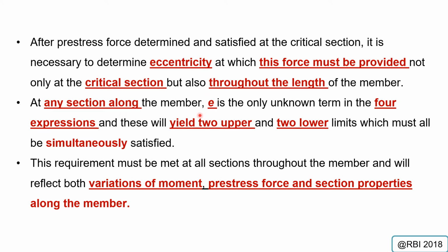Then we construct the tendon profile to determine the eccentricity at which this force must be provided. Okay, because we not only consider the critical section, but also the condition throughout the length of the beam.